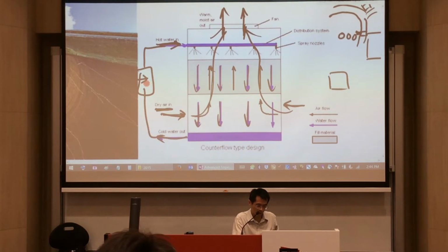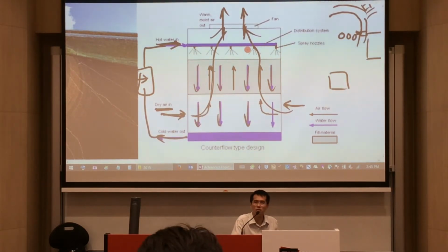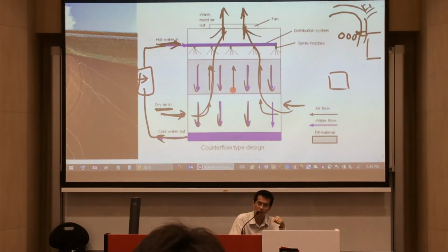Okay. So this place here may be your air conditioner, because your air conditioner will try to produce one side cold, the other side hot. So this hot side sometimes is cooled down by water, or sometimes it's just natural air convection. If it's cooled down by water, then this heated up water over here has got to be cooled down using a cooling tower. So you could see what is the energy consuming or electricity consuming device that can happen in a cooling tower.